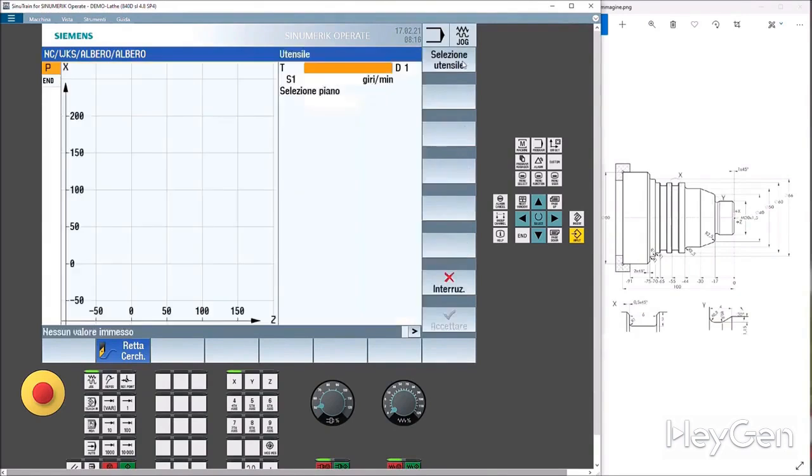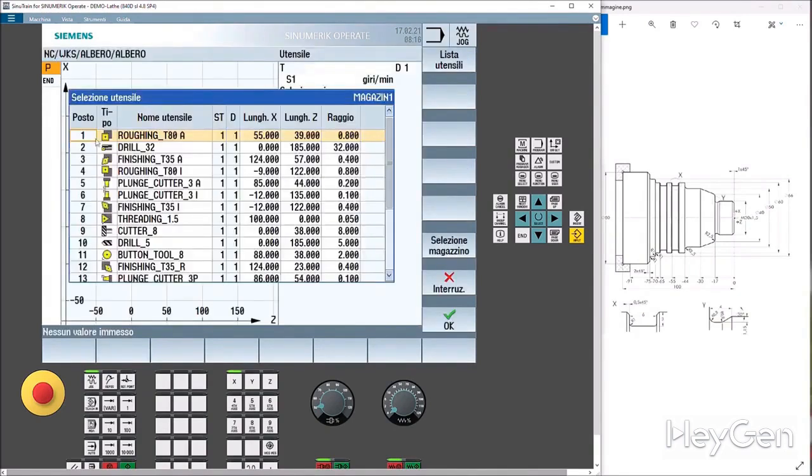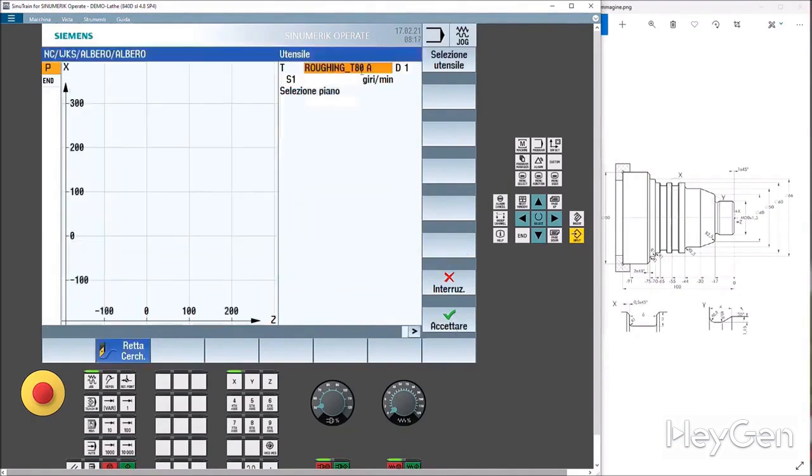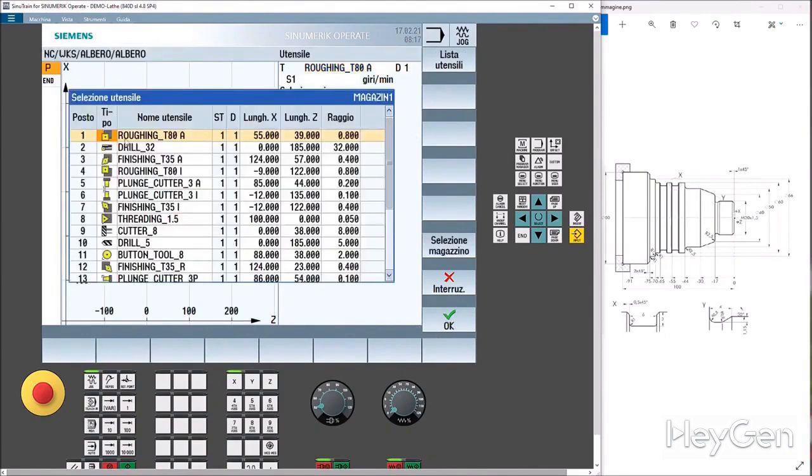Perfect. Let's press straight or circle, and automatically the menu changes. The first thing you do is what you do when programming in ISO, which is to select the tool and cutting parameters. First the tool, and then tool selection. It automatically takes me to the tool page, where I've already preloaded tools in the machine that will correspond to my turret, and I'm going to create my facing operation. So I select the tool store, choose the tool, and remember that we can also add comments.